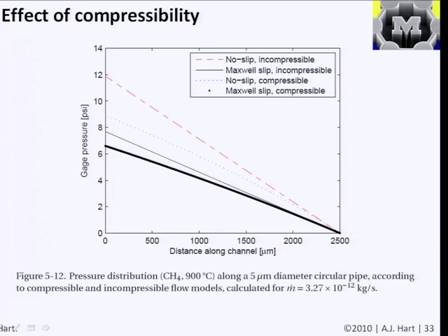And another thing that is important to consider is that as geometries get small, we have this great amplification of a pressure drop. So to force the same flow, remember it's like 1 over r to the 4th for our dp/dz, you can get relatively high pressure drops when you're putting flows through small pipes, meaning, and compressibility, of course, is only important for gases and not for liquids.